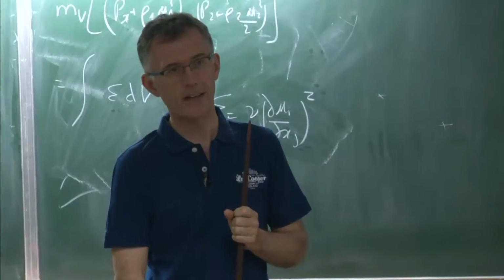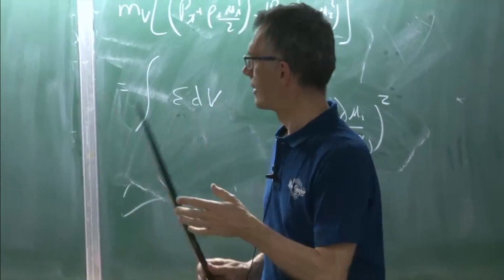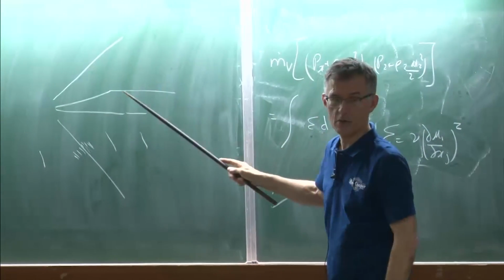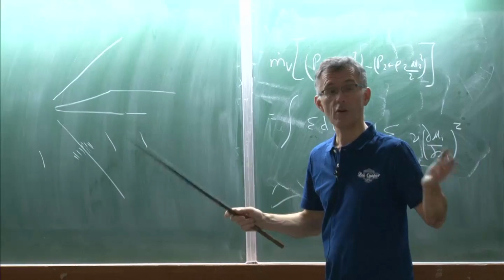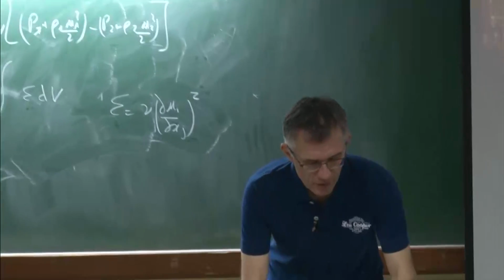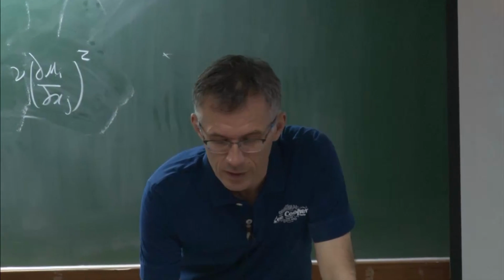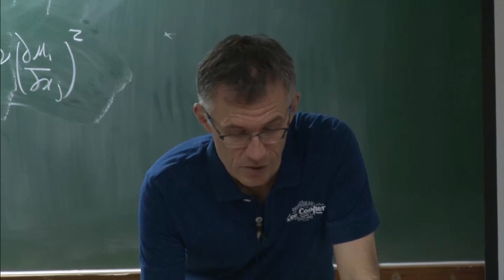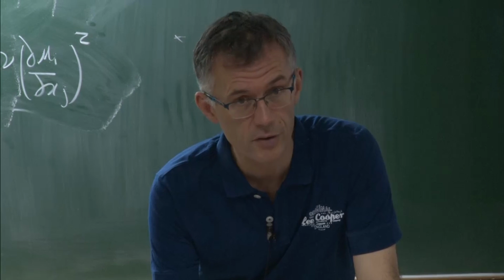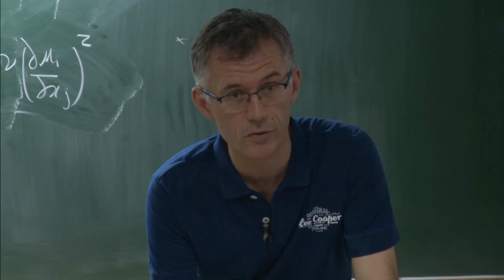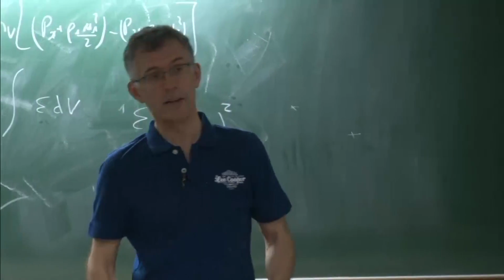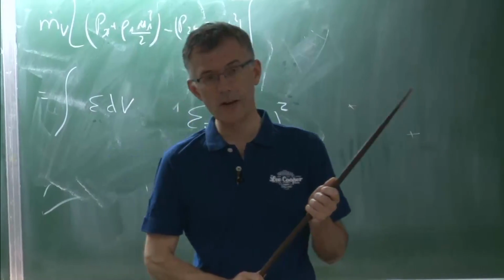But then afterwards, in a flow, whatever the flow is, for LES, you don't know where the mesh points should be. If you do an aircraft, you know that everything is taking place at the walls, so you put points near the wall. But in a combustion chamber, it's happening all over the place. I think I've shown you these movies when we looked at the flow in a turbulent combustion chamber, and you see vortices everywhere. So before you have done the LES, you cannot know where to put points. That's unfortunately the status.